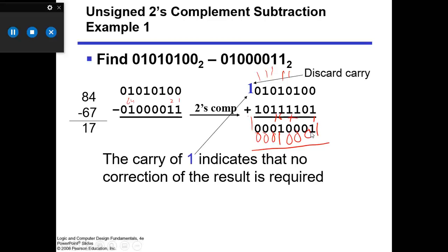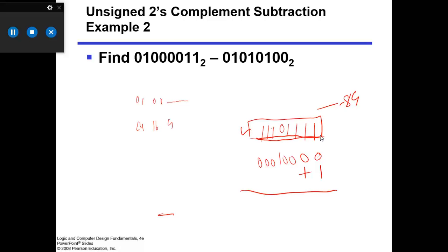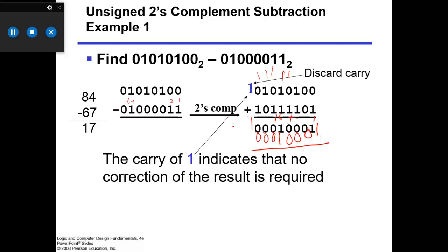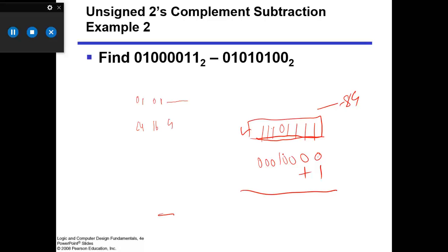You can see the result is 17: 1 2 4 8 16, 16 plus 1 is going to be 17. This technique is very useful for directly computing the binary results. We know that the weights go 1 2 4 8 16 32. So if a number is like 1 0 0 0 1, I can just put these weights, very easy to compute, and then add the ones. 1 is 1 and 16 is 16. So this is equal to 17. This is a direct way of seeing the binary values in your answers. Very easy to compute.